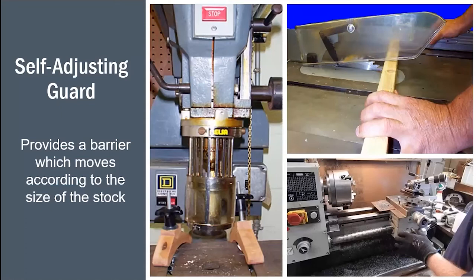Next category of guards is self-adjusting guards. These are, you know, a little bit more reliable because the operator doesn't have to think about using them. They will self-adjust. In this case, we've got a drill press guard here, a table saw guard, and a spiral accordion guard on the lead screw of the lathe.